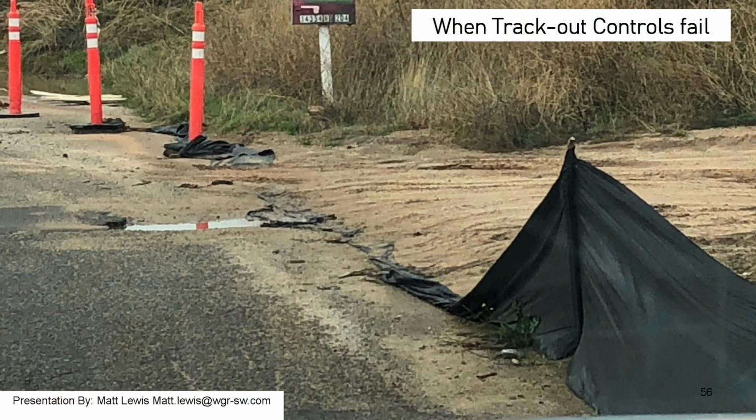This is also something you will see, where they have a nice perimeter control that, of course, isn't keyed in properly, but they'll just make up a new exit or a new entrance. They'll just run over the silt fence and start tracking it out into the street.